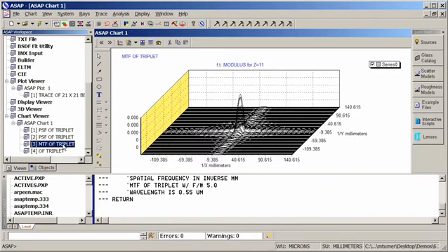and let's take a look at the three-dimensional plot, is the fact that this optical system designed to operate over a 30-degree field of view is not anywhere near diffraction limited, and we're seeing the effects of the aberrations in this optical system. And again, we can compare this to the lens design program itself and make sure that indeed the performance as defined by the ASAP system matches that created in the lens design code.